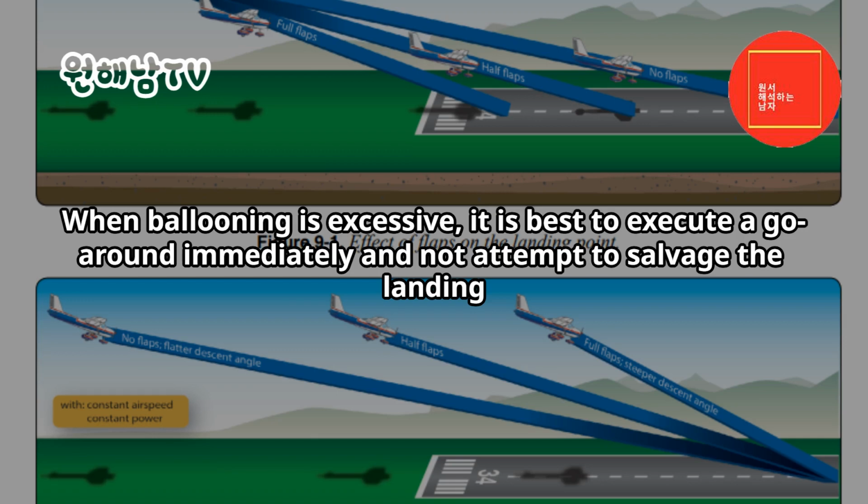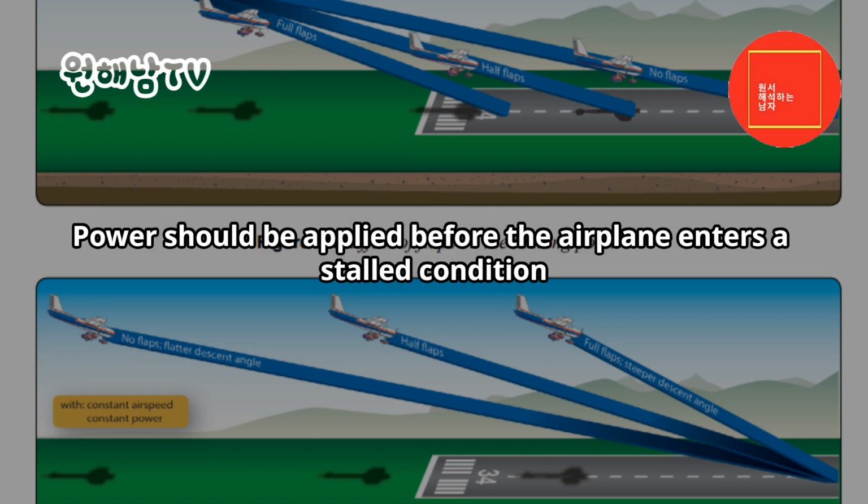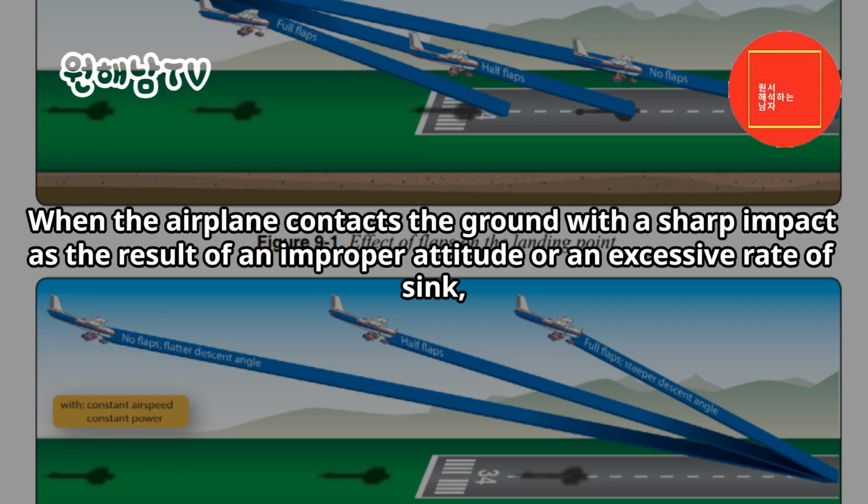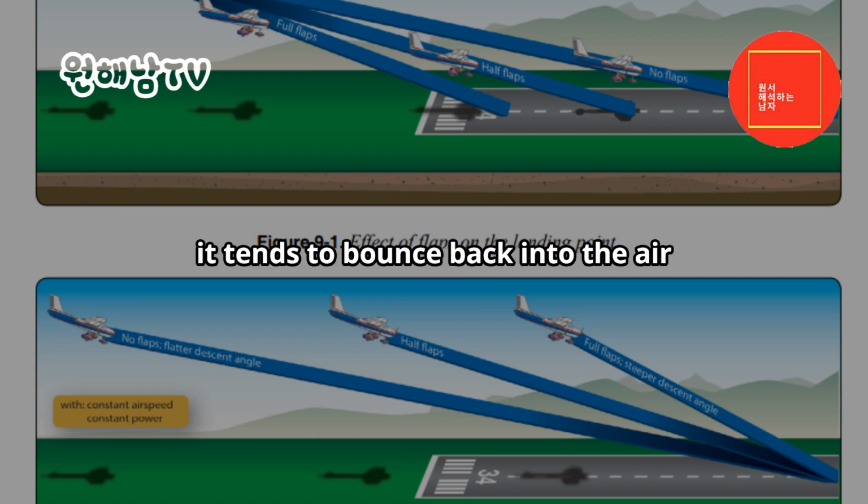When ballooning is excessive, it is best to execute a go-around immediately and not attempt to salvage the landing. Power should be applied before the airplane enters a stalled condition. Bouncing during touchdown. When the airplane contacts the ground with a sharp impact as the result of an improper attitude or an excessive rate of sink, it tends to bounce back into the air.